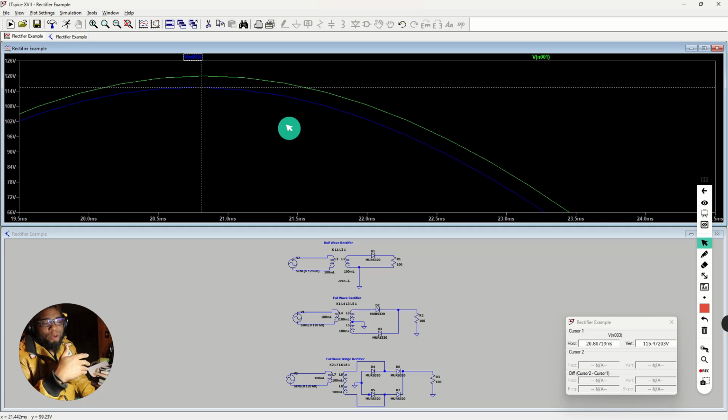That would null out the voltage drop, because you would have a capacitor on there that would likely exceed the amount of voltage that you were desiring in the first place, right? So if we had a capacitor on this, we could very well get 126, maybe 130, though 130 would be pushing it, but something like 126, even with load on it. Once we have a load on it, 123 volts, something like that.